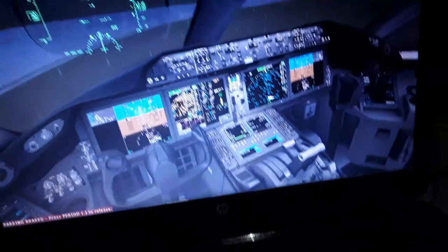So we have also the HSI, the horizontal situation indicator with the integrated display of the flight plan. We have the standby flight plan. The navigation display displays the GPS, the inertial reference position of the aircraft, the terrain, and the weather reflections from the weather radar. You can see the terrain map with the airports named, the runways we're gonna use for takeoff and for landing.